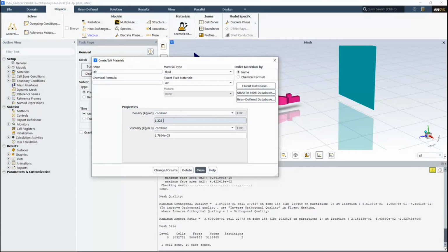That's important because air is actually a compressible fluid, but it only is relevant to be treated as compressible for the purposes of a simulation when we go above Mach 0.3. When we go above 0.3 of the speed of sound, then we need to consider things like compressible gas, where we might do an ideal gas representation where we know PV equals MRT. That's the ideal gas equation, and that means we're solving for things like density. We need to make sure we have temperature or energy turned on. In this case, because we're not solving any compressibility and we don't have any heat transfer, we don't need energy turned on, and we can have a constant density. So that simplifies things greatly.